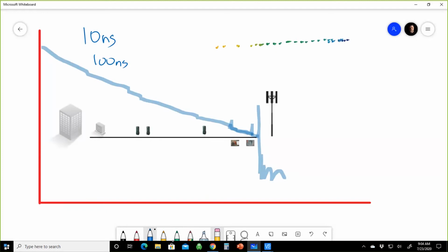Spatial resolution is the ability to measure close events, very close events, 2 very close splices, 2 very close connectors within a tie cable, those types of things, right? And in a long haul network, if you're testing 100 kilometers, roughly 60 miles, you're using a super long pulse width. That's over 1,000 feet long in pulse, right? It's really, really long. And the pulse is your resolution. And so that's your sampling.